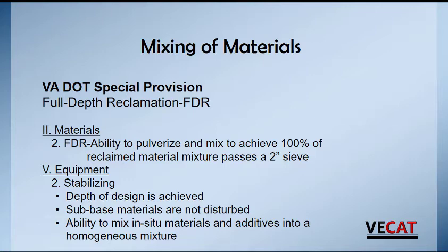Here's another shot of the VDOT specifications. So we have to be able to get 100% passing on a 2-inch sieve. So gradation becomes a very important process. We have to pay attention to it. Like I said, use the tools we have to control it.